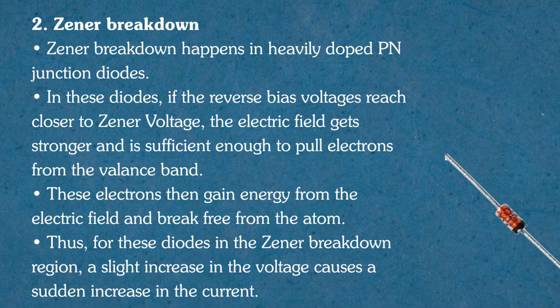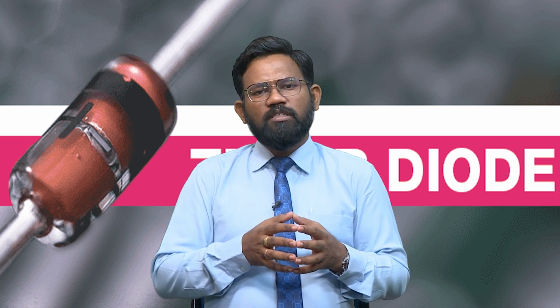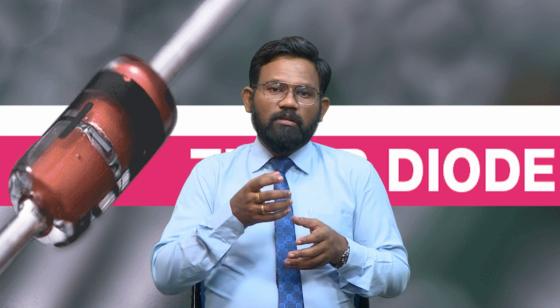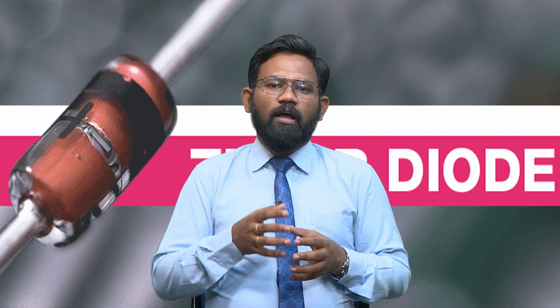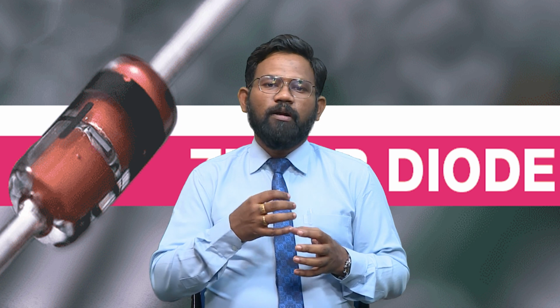Thus for these diodes in the Zener breakdown region, a slight increase in the voltage causes a sudden increase in the current. If we further increase the voltage, a very slight increase will cause the field to get much stronger, and that pulls the electrons very easily from the valence band to the conduction band.